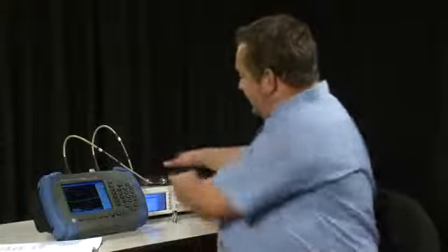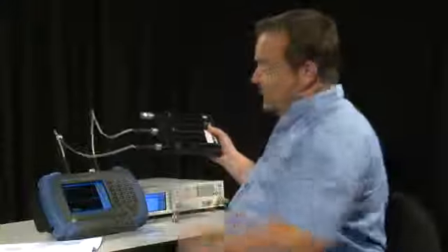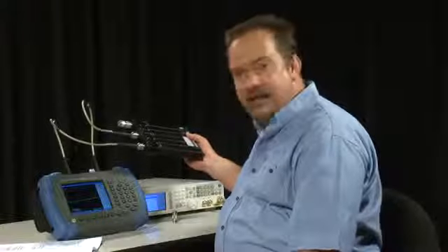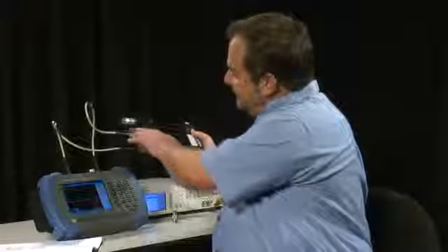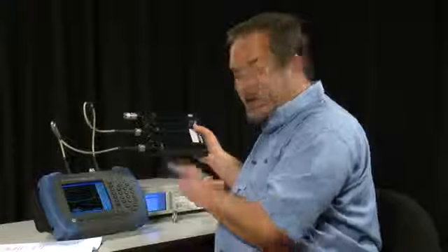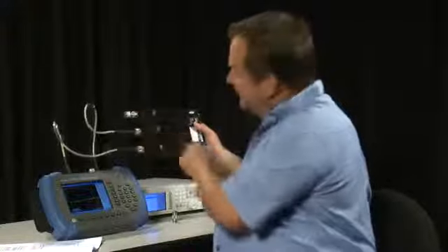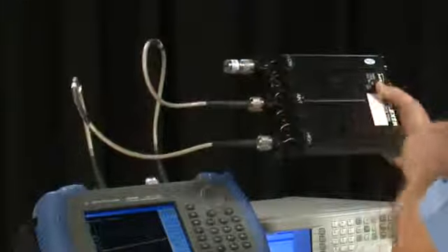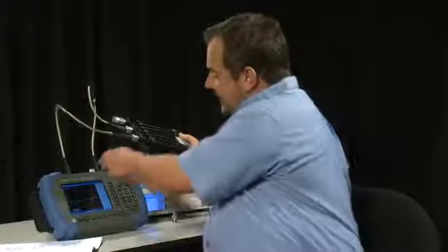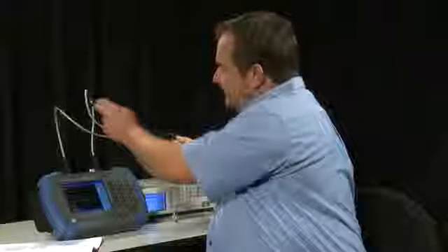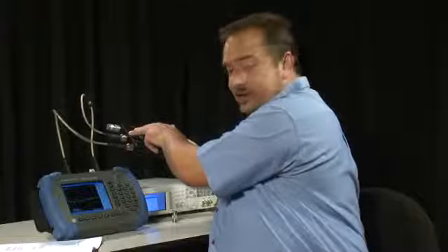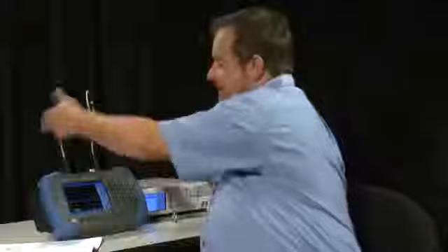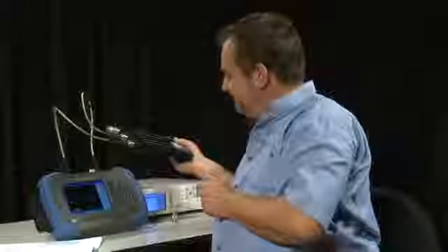So what I have with me here is an RF diplexer or duplexer, which is a filter that's commonly used in base stations for separating the receive signal from the transmit signal. Now this is actually two filters, so if you're going to use one of these as the device to measure, be sure you terminate the third port with the 50 ohm load as I've done here. So we have the tracking generator signal coming out of the N9340B into one port of the filter, and then the modified signal coming from the filter back into the spectrum analyzer.